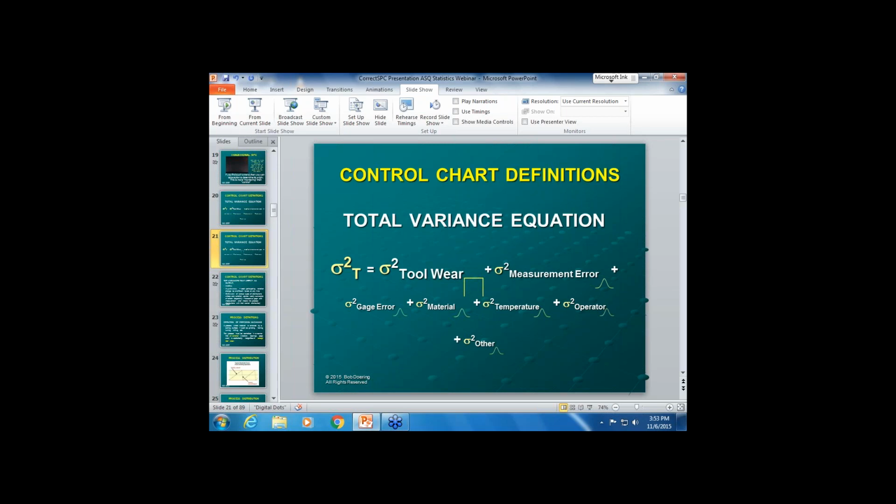But it is good to recognize that neither the uniform distribution nor the normal distribution, the Gaussian curve, is appropriate for either one of those. So you do need to do your capability studies based on the correct distribution, and do a distribution fit to find out which one is correct for the variation that you're seeing. And controlling it takes a different methodology, and I guess I need to look at that as a separate presentation because we'd have to go through a whole new thing.